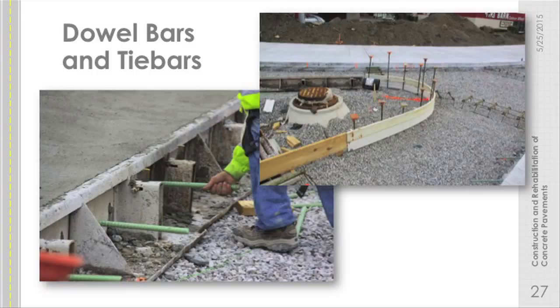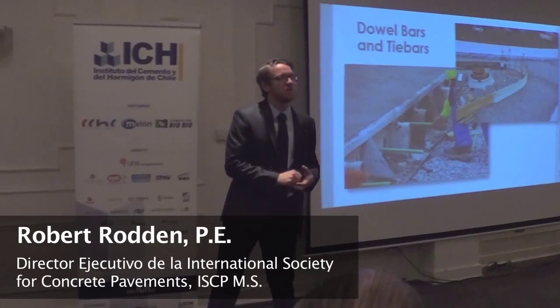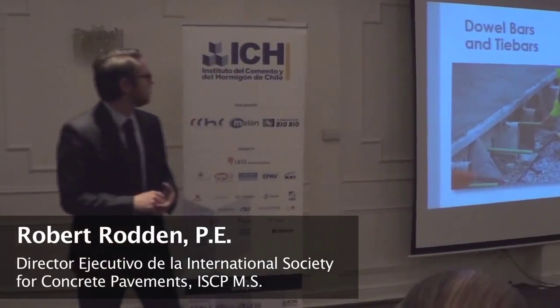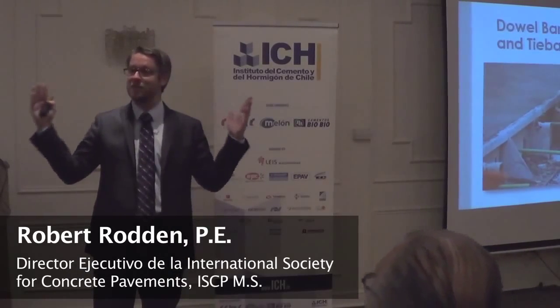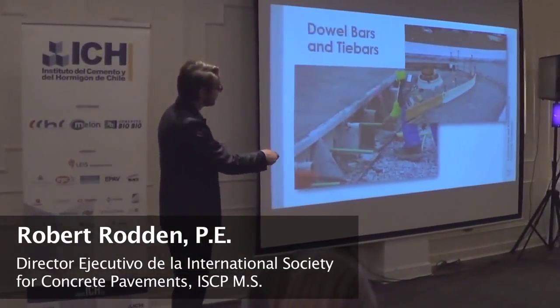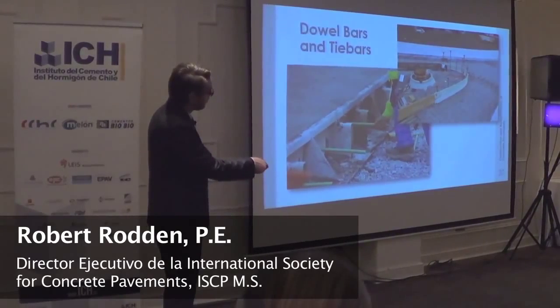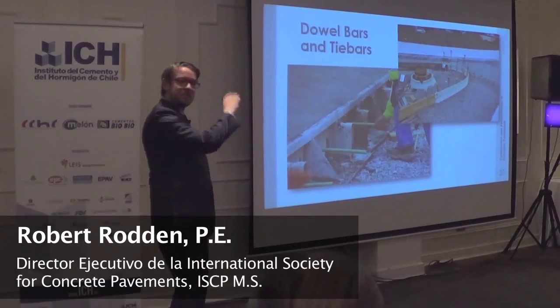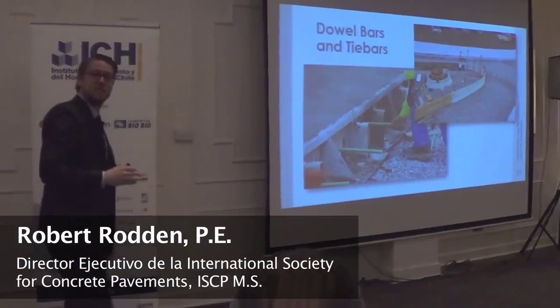Once it becomes thick enough, and this section was about, what was that? Oh, it was a little over 20 centimeters if I had to guess from memory. Once you get tall enough and the concrete is relatively fluid, it has a high slump, there is a fair amount of formwork pressure. So you can't just use any forms. These have to actually be engineered and supported somehow, which is why these steel forms have such a wide footprint to help resist that bending over, that spinning over of it.